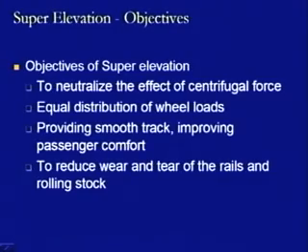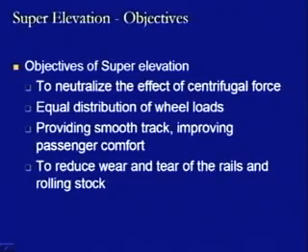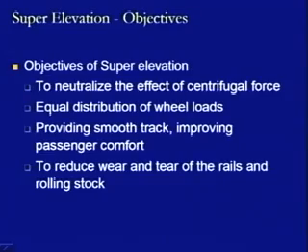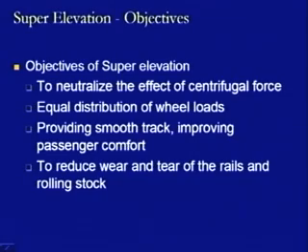This is another objective, because the super elevation, once provided, will nullify the effect of centrifugal force, which tries to take the system in the outward direction. Therefore, a jerk will be felt as soon as a wagon or the rolling stock moves from a straight section, where there is no centrifugal force acting, to a curved section where all of a sudden a centrifugal force starts acting in the outward direction.